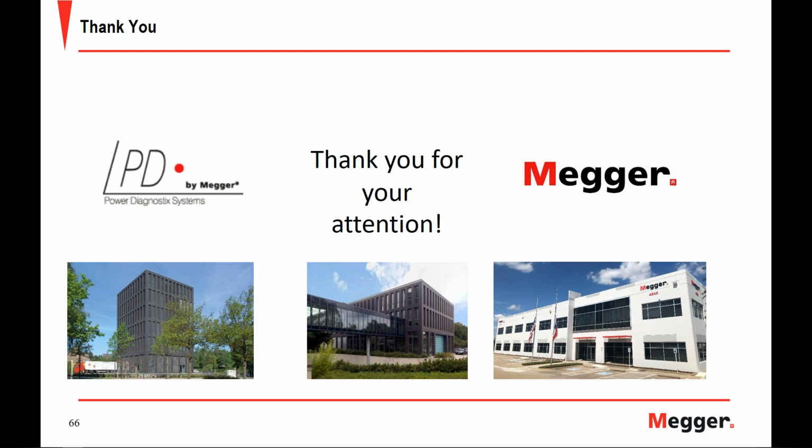All right, thank you. Charles, is it possible to establish a relation between offline and online PD tests? Are those results comparable? It's a little difficult to establish a full relation between the two, as Jeroen just mentioned earlier. There are different conditions, such as your no load or cold conductor condition, and there are going to be slight differences, though the results will be comparable on your phase resolved partial discharge patterns.